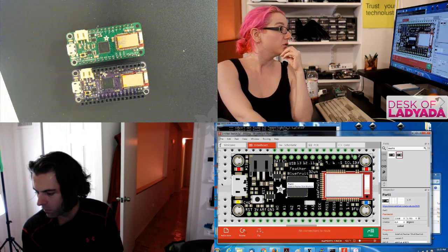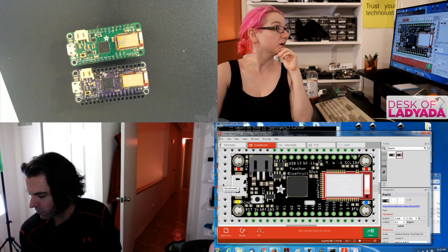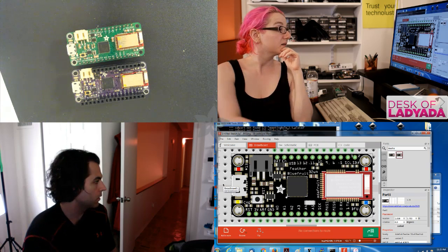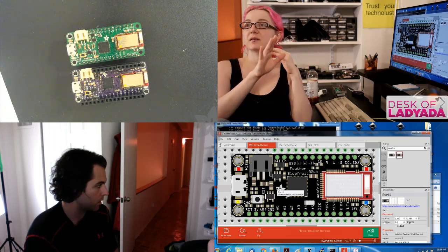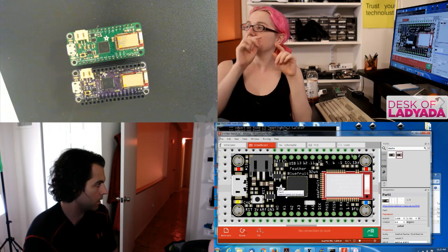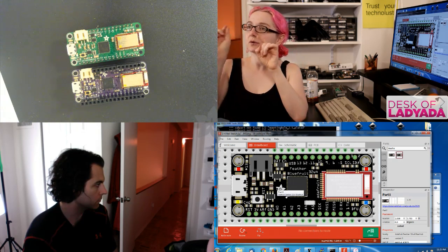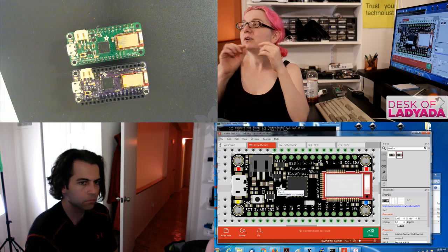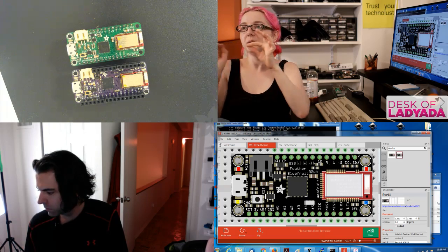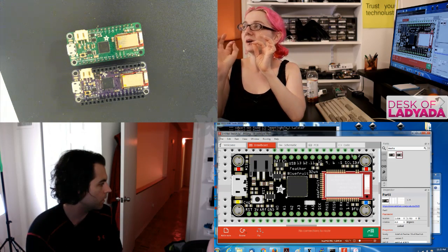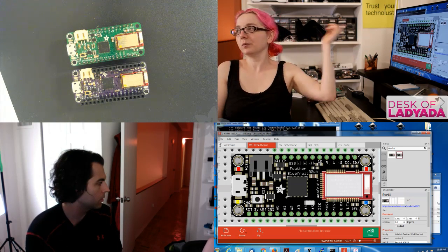These are tuned for the Adafruit parts, but still, it's really lovely. And it even has a little Adafruit logo, which is just hand entered. He made an exception so that it's not rastered. Because usually it's Gerber rastered, where a drawing on a PCB is little rectangles. He took all those out and replaced it so it wouldn't be too big.